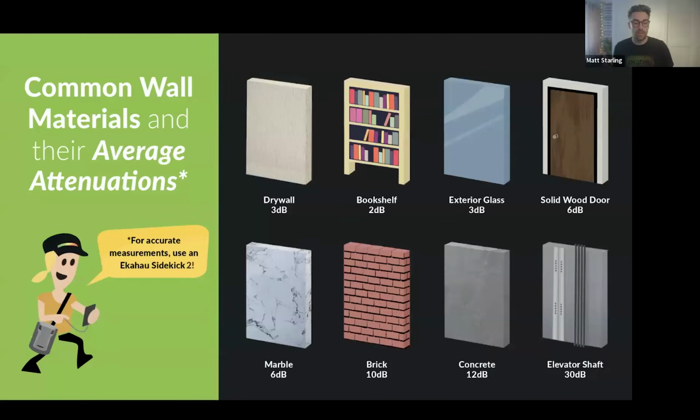Right. So the next thing that we wanted to talk about is the wall attenuations. And a classic Wi-Fi design process that we go through is we load our floor plans into our predictive model, and then we have to start drawing walls, right? So that we can model the attenuation of the RF signals as it propagates our environment.